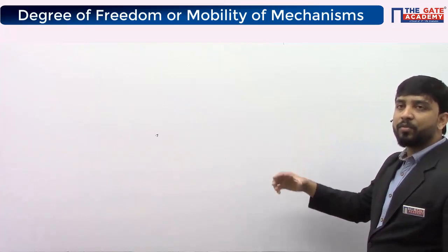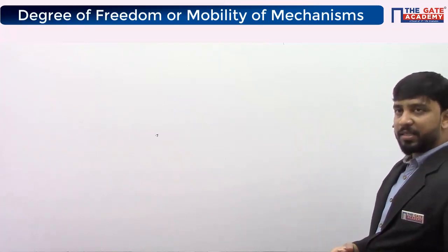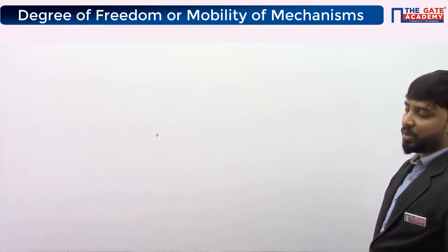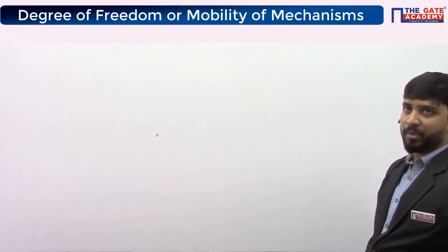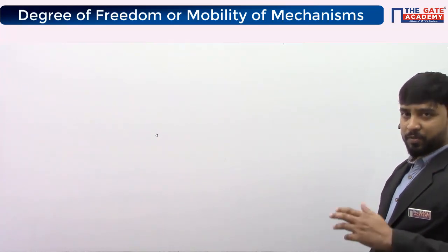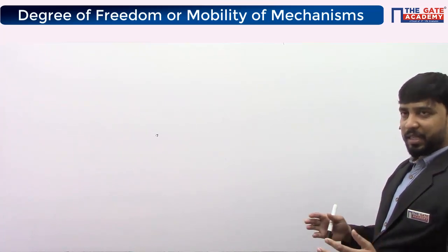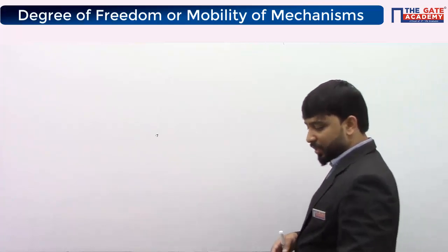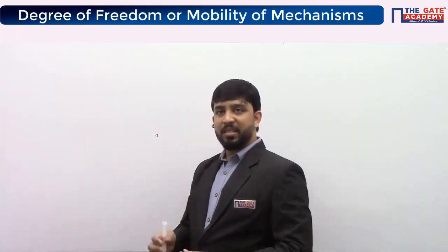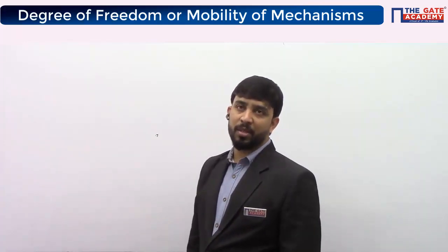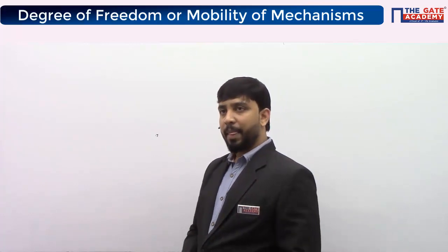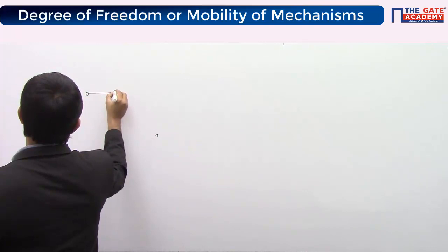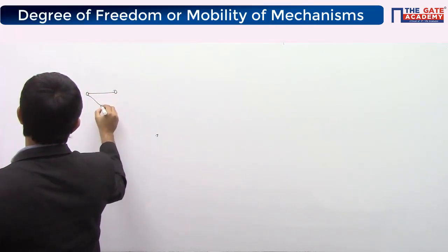Those are the 3 degrees of freedom, and internally inside the kinematic chain you may have some more degrees of freedom. Yesterday we solved one problem for calculating degrees of freedom for a kinematic chain. We got degrees of freedom as 5. I told you 3 degrees of freedom is the combined chain can move in 3 possible directions, and the remaining 2 degrees of freedom is inside that chain you can have 2 possible arrangements of links. Okay. So for a kinematic chain, minimum degrees of freedom should be 3, okay?